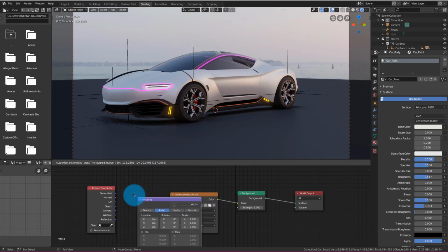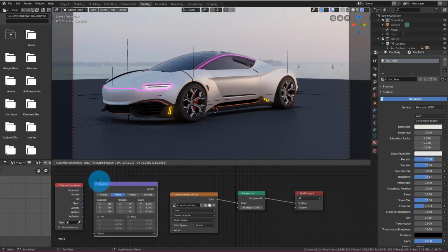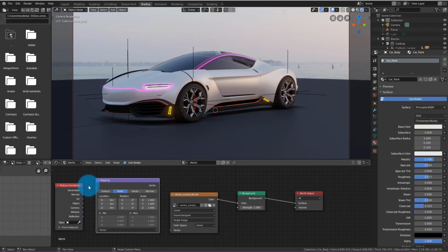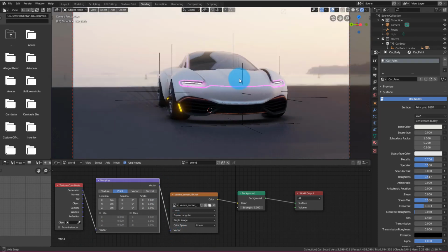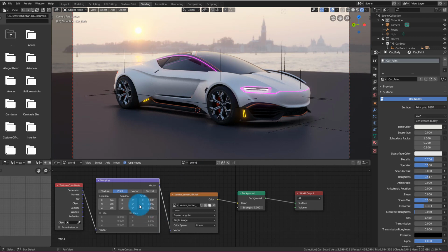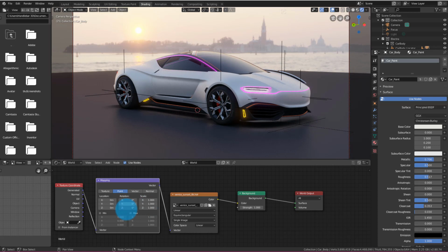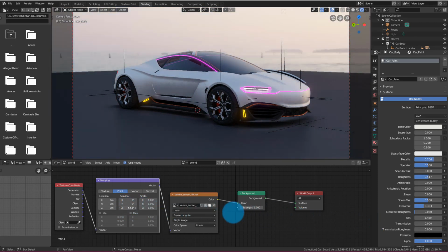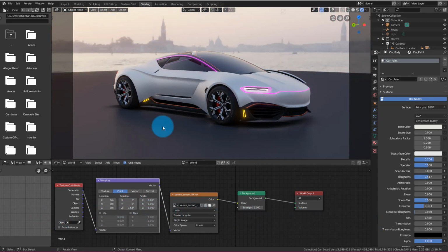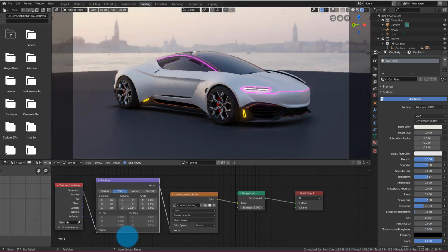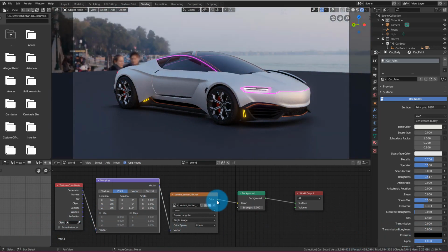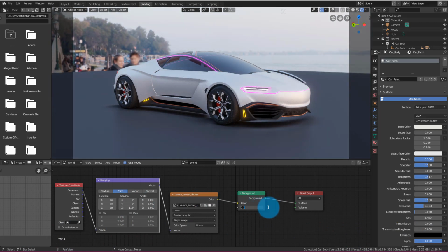And so this will give us the ability to move the texture coordinate of the HDRI around. So we have to connect generated to vector, and then the vector to the other vector in mapping to the HDRI. So now if we select the different axes of rotation, here I did Y. If I select the Z, now I can rotate around the environment. And I know that seems like a very long way of doing that. But we're actually going to start working with these sorts of nodes more when we do the street. So it's important to start understanding this.